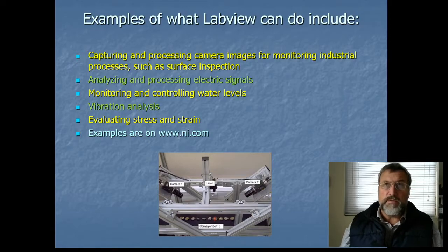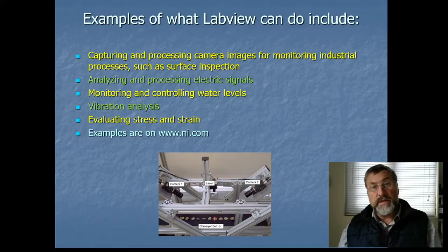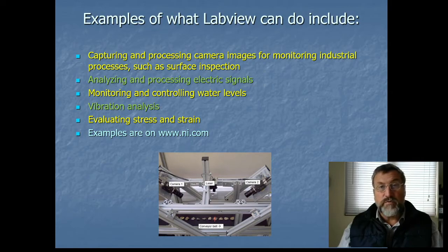It's not so much designed for in-depth analysis. That would be more like MATLAB, for stuff like neural networks and so on. But LabVIEW is pretty good because it comes with a VI which allows you to run a MATLAB script, which is useful because you might want to run a script which is running, say, a neural network. You wouldn't try to code it in LabVIEW. You just send the data to the MATLAB script, run it there, and send the data back to LabVIEW again. And we've used that in the lab actually. Gary Atkinson, who originally built the photo face rig in 2007, did some of that for some analysis in that project we had at that time.